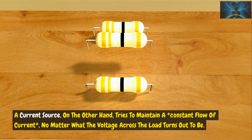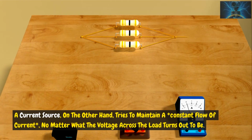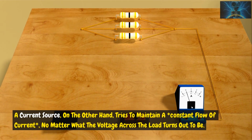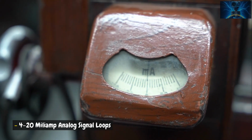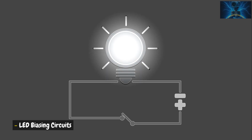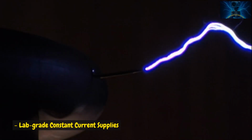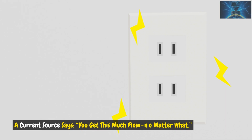What is a current source? A current source, on the other hand, tries to maintain a constant flow of current, no matter what the voltage across the load turns out to be. Examples: 4 to 20 milliamp analog signal loops, current loop calibrators, LED biasing circuits, lab-grade constant current supplies. A current source says, you get this much flow, no matter what.